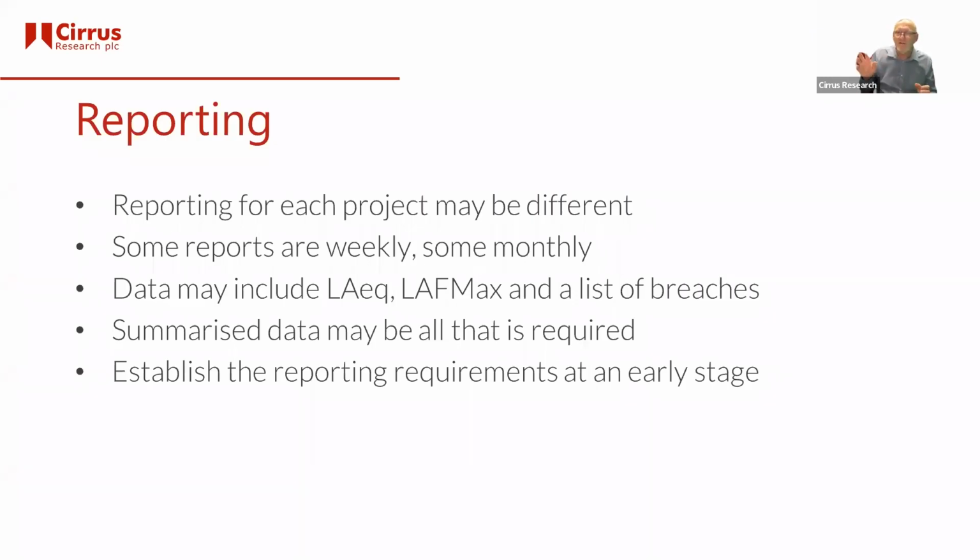So you've got graphs of daily, maybe hourly data of the LEQ, and maybe some maximum levels in there as well, and looking to see what the daily average was, as well as the hourly average, and a detailed list of breaches, etc. So it can be very, very varied. So having the ability to produce that information from whatever system you've got is key.